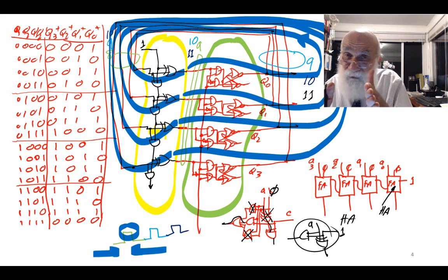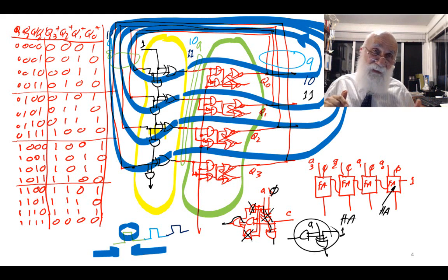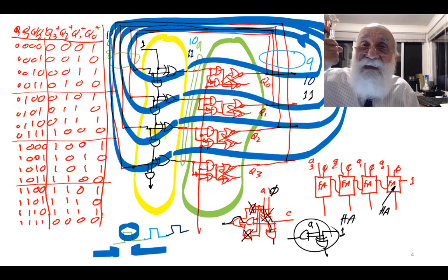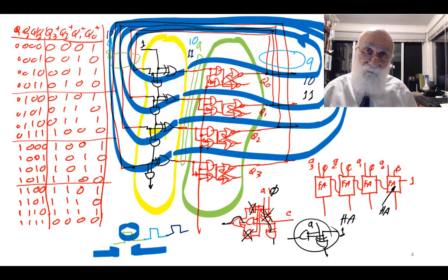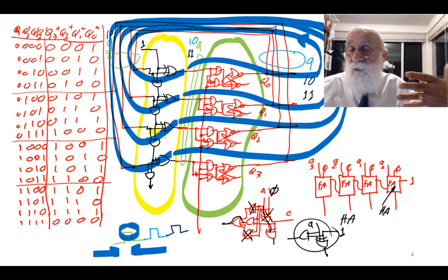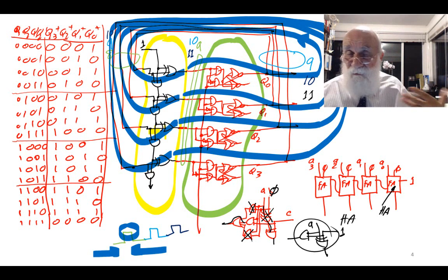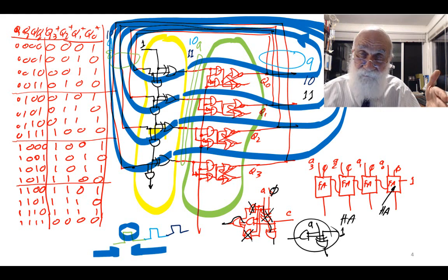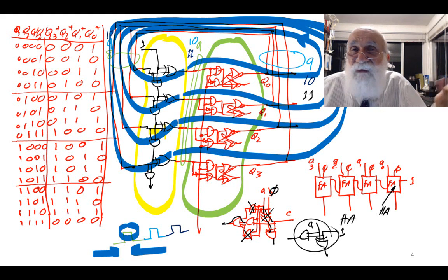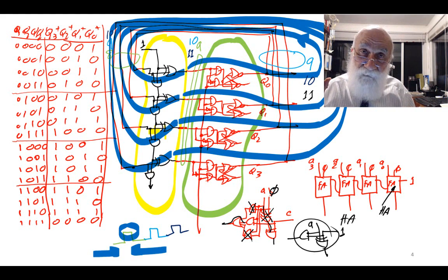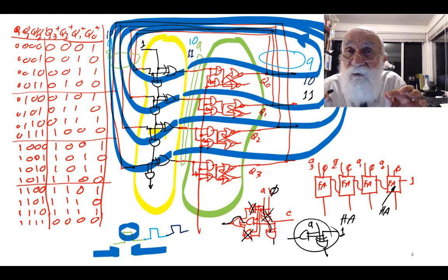Unless I let only one propagation go through and then stop it there. Now, the reason for oscillation is because it is transparent. Because the input sees the output, or the output sees the input, whichever way you want to look at it. So there's nothing I can do with this. Okay? Unless I keep my clock exactly short enough so that only one propagation goes through.